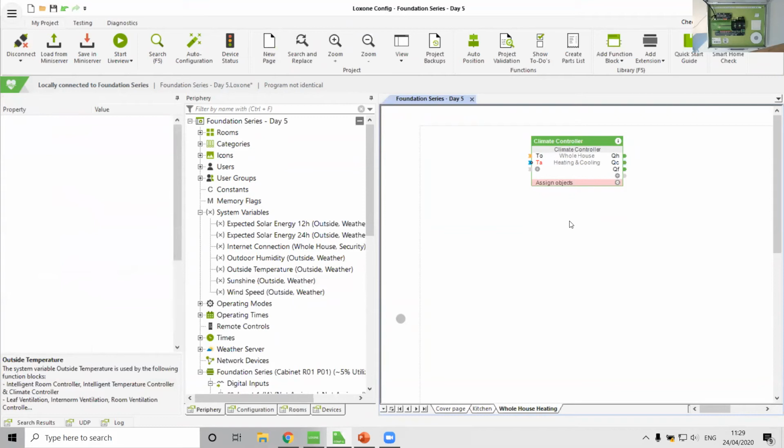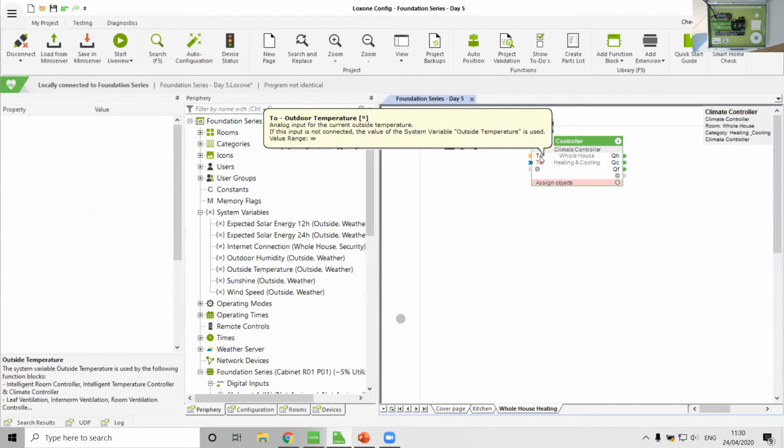So as an example, the airflow MVHR unit that I've got right down there has a temperature sensor built into its inflow pipe, which I can read through Modbus. So at my house, I've defined it by logic and I'm reading it from the MVHR unit. But it is quite important because weather compensation allows us a more efficient heating system. Basically, no matter how well insulated the house is, the greater the difference in temperature between inside and outside, the greater the rate of heat loss will be.